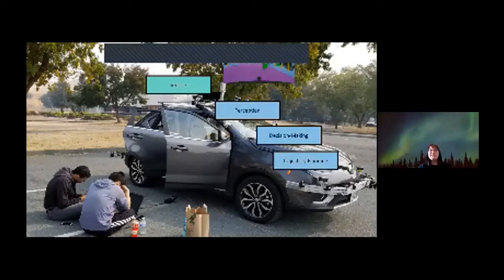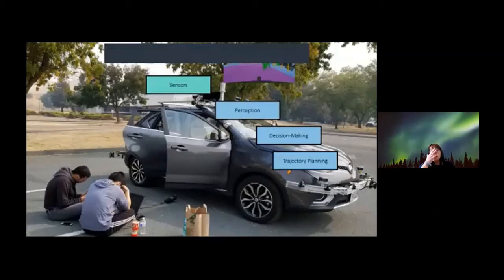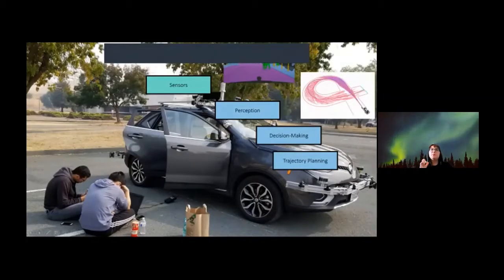So this is going to take these commands or actions and try to turn them into the physical motion or movements of the robot. So if we are told that we should change lanes, this will actually be saying how we should do it. What is the trajectory and the motion that this robot should actually follow? So this planning system not only needs to consider the obstacles and constraints from the perception system, as well as the guidance from the decision making, but it also needs to understand the physical constraints of the vehicle. So when we're considering these trajectories, we hopefully are already considering the fact that our car can't move directly side to side, but we need to have feasible or achievable paths. So the output of the system is going to be some trajectory that we can follow and often looks into the future. This planning aspect looks forward in time and tries to think about how we will move and how we will navigate through the world.